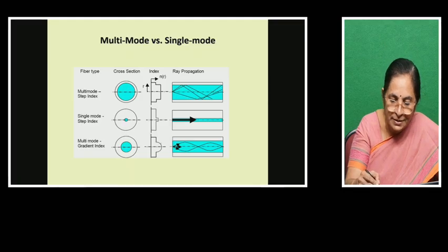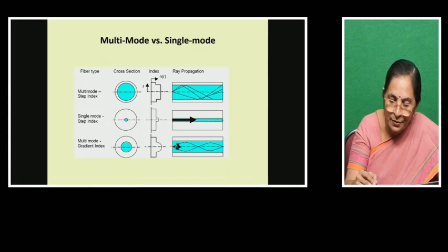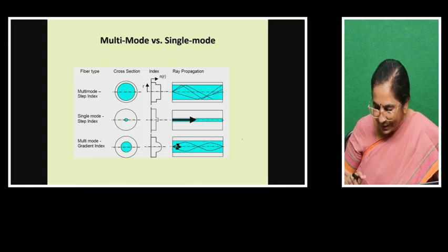Okay, so it is gradient. You can see the signal given here will be just traveling like this, whereas in multi-mode graded index, based on the refractive index of the core, some rays will choose a straight path, some will have the angle of incidence upward, meaning it will be taking a path like this. So they will be safely traveling to the other end.